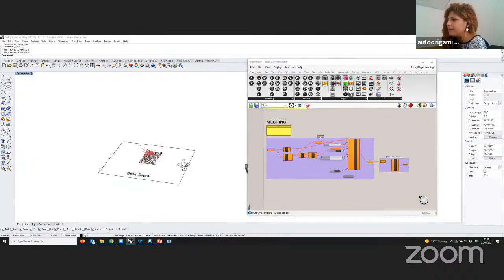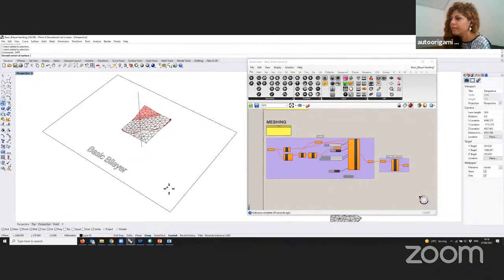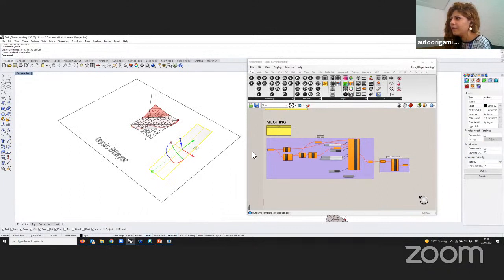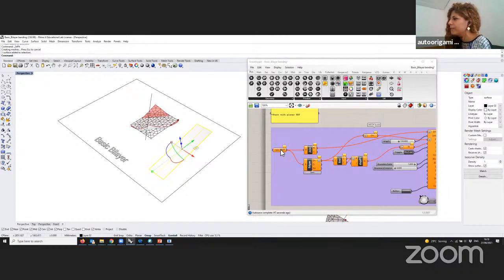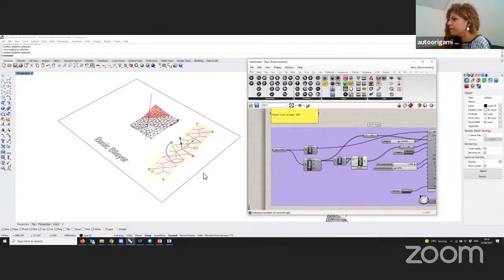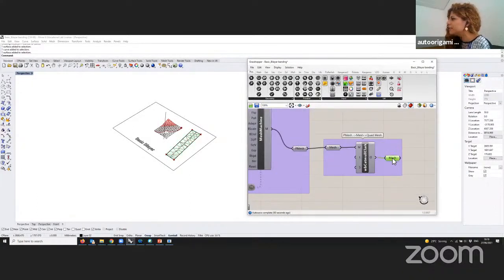So the way this step works is that you can draw the surface that you want in Rhino. So I'll draw something like this. And the surface that you have in Rhino, you come and you reference here. So I click on it, come here, set one direct. And this component, again, there is a reset button, so you reset it. And then this gives you a mesh. So what we do here is that we bake this mesh to send it to Rhino.